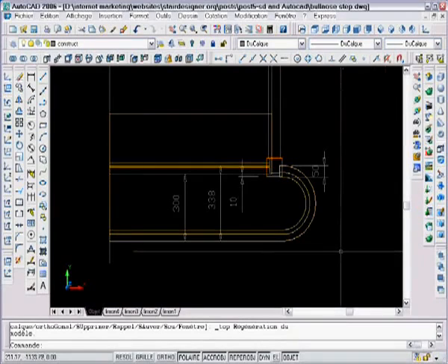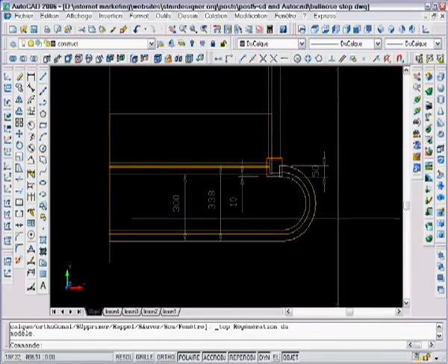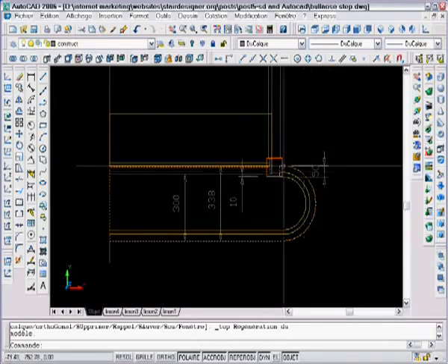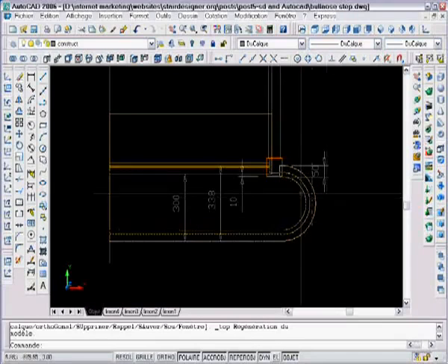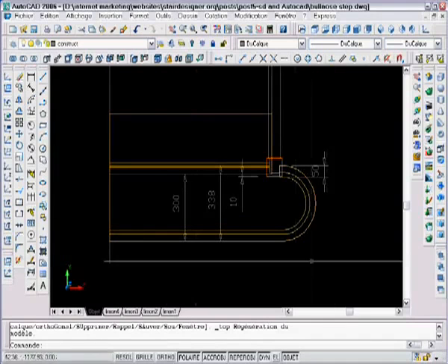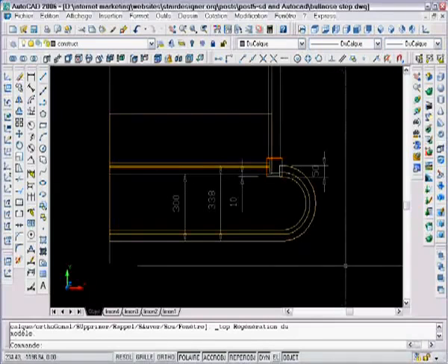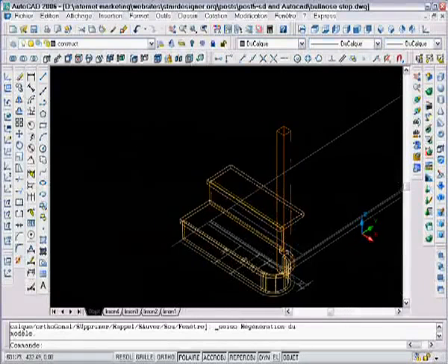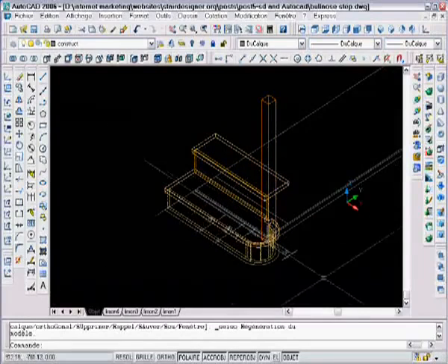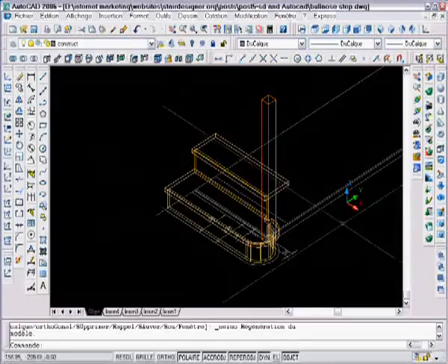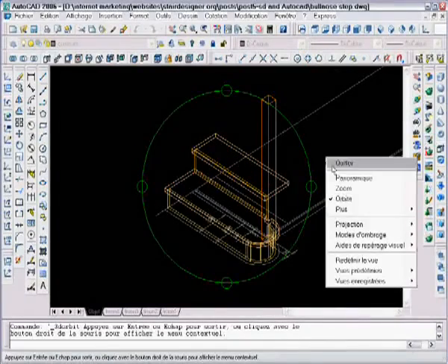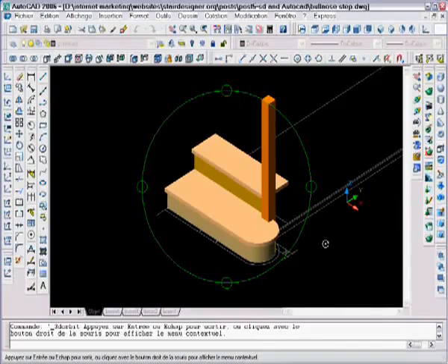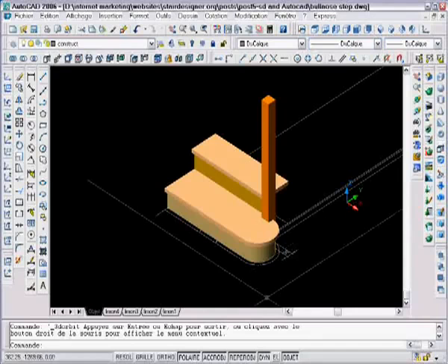In general, I like to make the first step a little bit wider than the other steps, and I like to put a curved riser, and the bullnose assembles on the exterior side of the newel post in a specific way. This is the actual plan which I draw up in AutoCAD. Here is the starting step with the first and the second risers, just to give you an idea of how I like to build this. If I show you with some 3D, it gives this sort of effect.